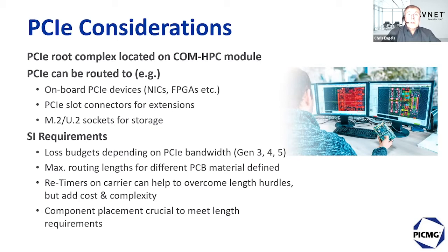It provides you a lot of connectivity in terms of external network controllers, FPGAs, additional PCI Express cards or storage cards you would like to connect. But as said, in terms of signal integrity, you have to respect what the specification actually provides here in guidelines in terms of maximum trace length and loss budgets.